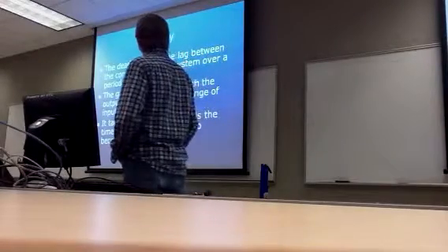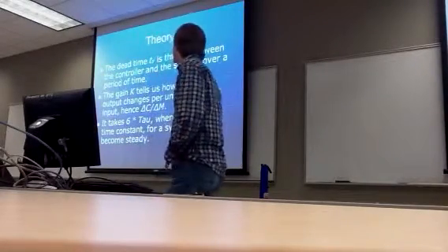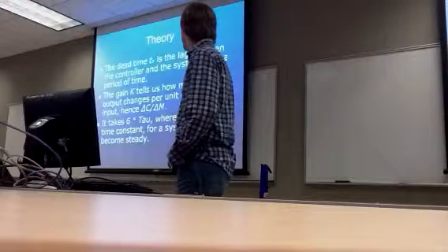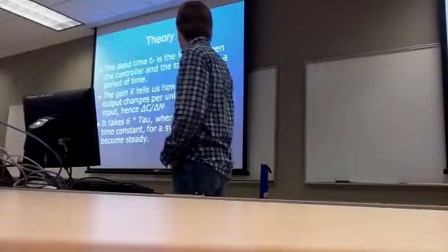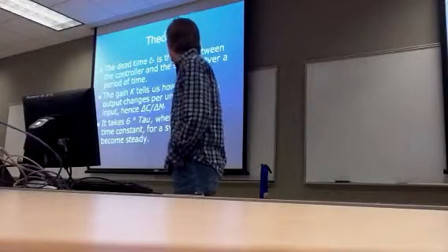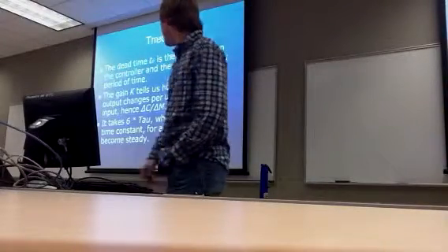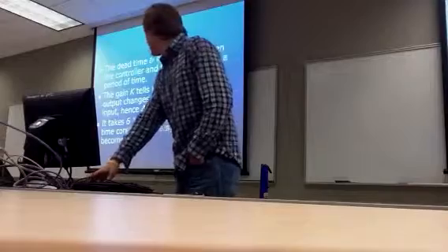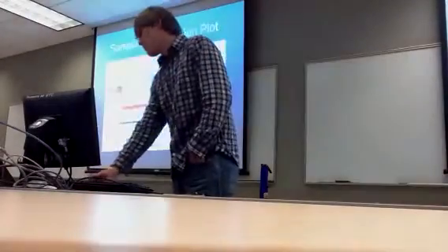Dead time is the lag between the controller and the system over a period of time. The gain tells us how much output changes per unit change of input, and the time constant tau, and it takes 6 tau for a system to become steady.